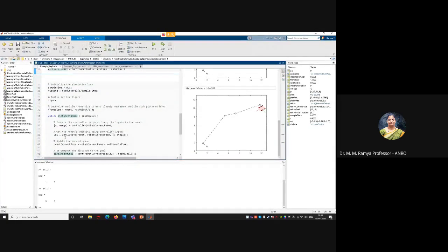Now comes the actual simulation. Now what I do here is, for the entire simulation or the entire kinematics, I set how frequently you want your controller to work, or how frequently the sampling has to be taken. This is like when you do a signal processing application, and you keep getting signals, and you are trying to set a sampling frequency. What does that mean? When you get an entire signal, at what frequency level you want to pick up one sample from the actual signal.